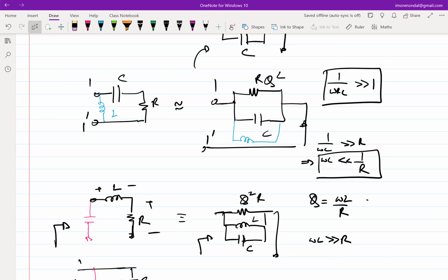So even though in principle it seems like you will be able to transform any impedance to any impedance, which means that in principle, I should be able to have any Q, it comes with a cost. If your Q factor requirement is large, if you want to transform a 5 ohm impedance to a 50 ohm impedance or a 1000 ohm impedance to a 50 ohm impedance, then your Q, which is under root the ratio of the impedances effectively, will determine the loss of the system, right?